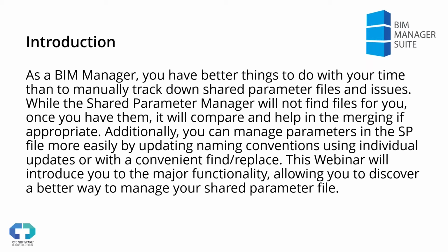It doesn't let you find files, doesn't let you easily compare things side by side, doesn't let you rename parameters, and a lot of that stuff are things that we need to do on a regular basis. I also don't have the ability in that out-of-the-box tool to find and replace things, right? So I'm going to show you how Shared Parameter Manager, once you have your shared parameter files internally, once you have the multiple files or even the one that you've got, can help you manage that shared parameter file set, bring it into one, and really update those parameter names as efficiently as possible.